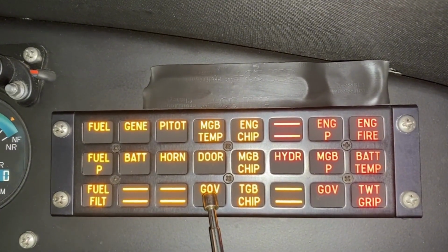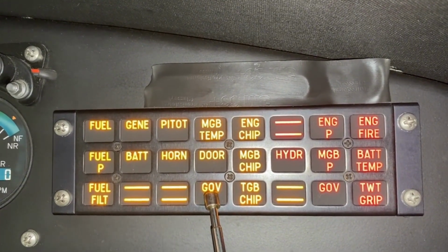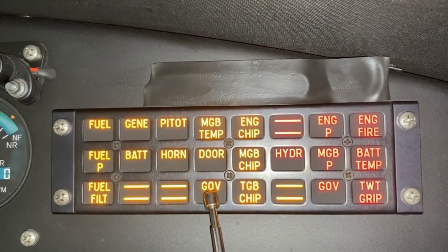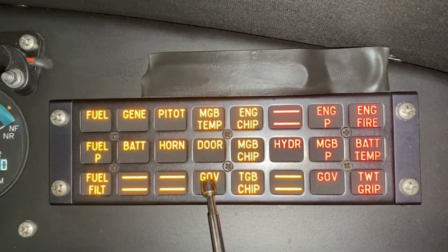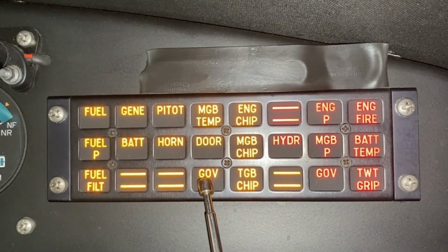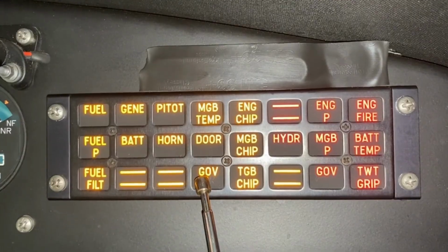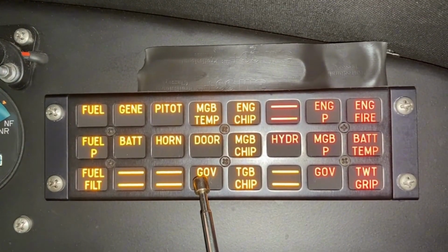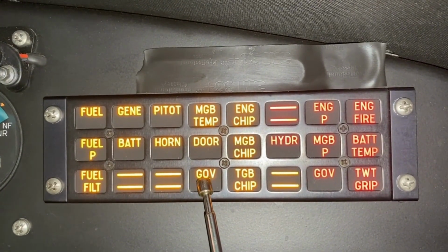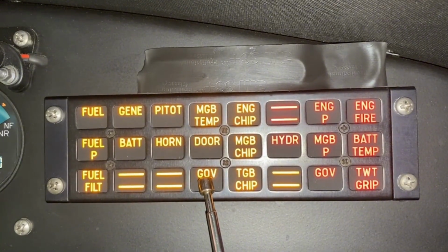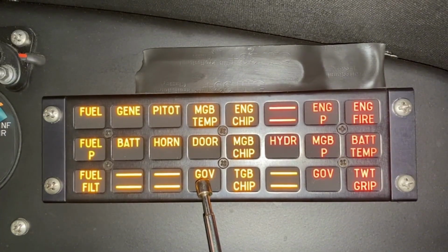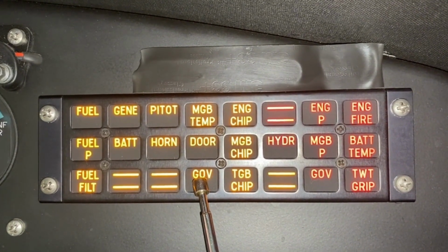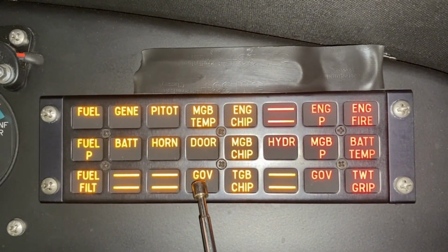So we have 3 levels of failure, right? The first level is when this golden light starts blinking, which we call a redundancy failure. Basically the degradation is 0 and the light keeps blinking. However, when the pilot sets the throttle lever to the flight condition, that is twist grip, the light goes out, but that doesn't mean the failure is gone. Then there's another malfunction where the yellow light comes on, right? There is a degradation in the engine, but it keeps working.